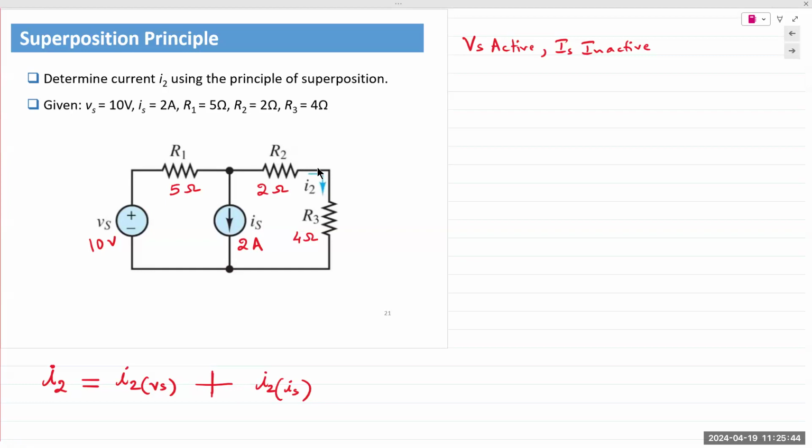And again, if I wish to verify my answer, I could do superposition. As an engineer, if I saw a circuit which has 3 sources or less, I might tend to use superposition, because the obvious downside is for every single quantity, you have to perform n number of analyses.